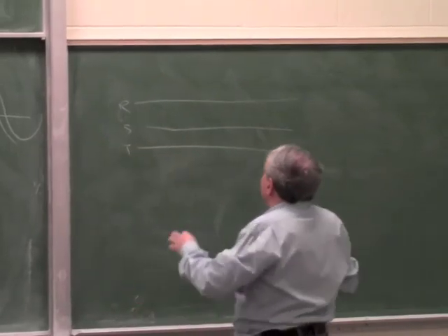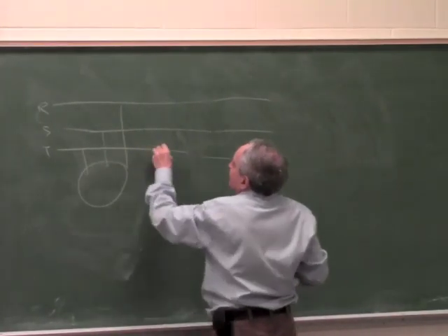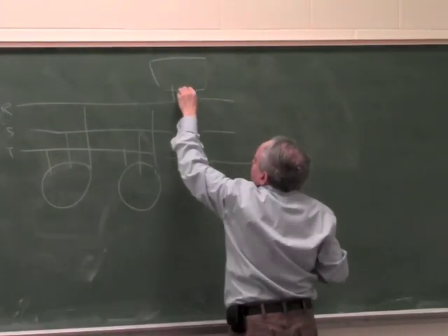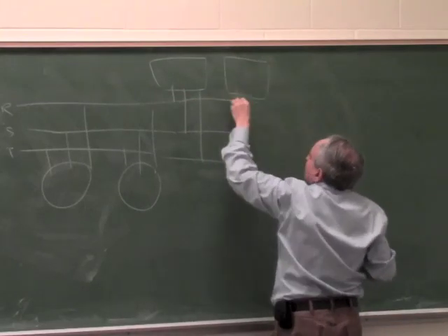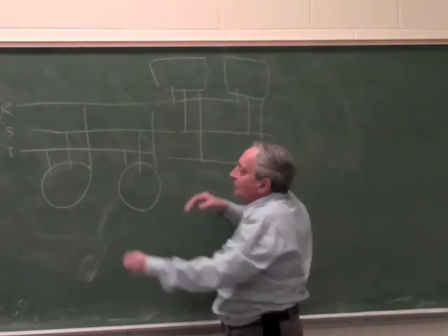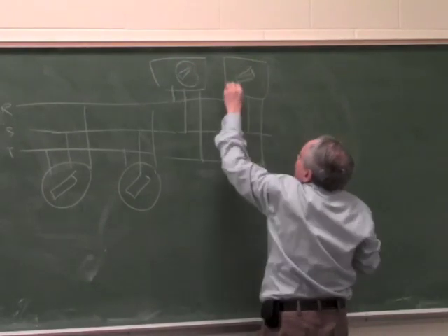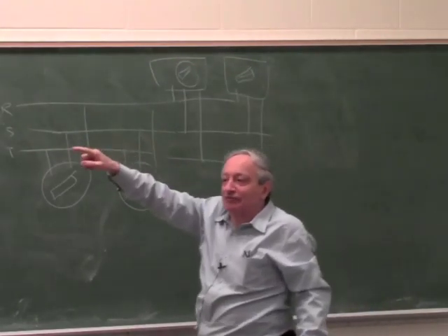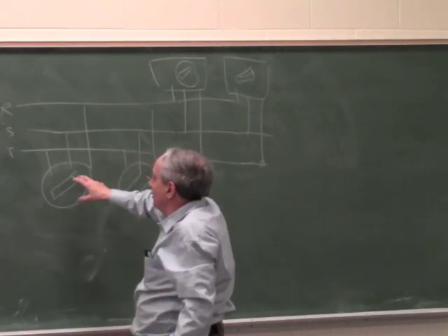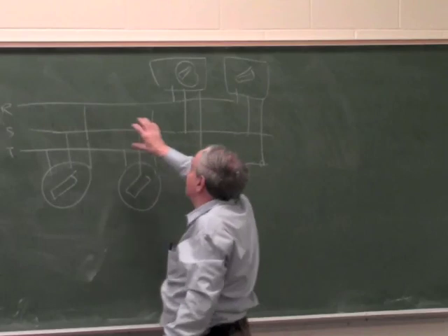So it means if you have a national grid, and you have many motors connected to this grid, and you have many power stations connecting to this grid, and some can be water, some can be steam, all these motors and all these power station armatures behave as if they were geared together on one long shaft going through the whole country. And if you take the load off one and try to make it spin faster, all this power goes directly back into the grid and reduces the load on the power station.